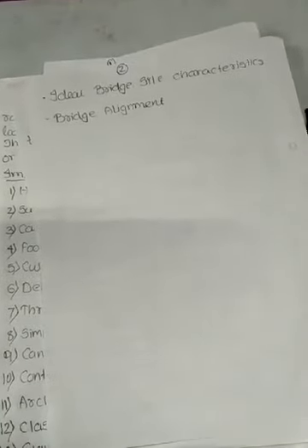In square alignment, the bridge is at right angle to the axis of the river. And in skew alignment, the bridge is at some angle to the axis of the river, which is not a right angle. As far as feasible, it is always desirable to provide square alignment. The skew alignment suffers from the following disadvantages.